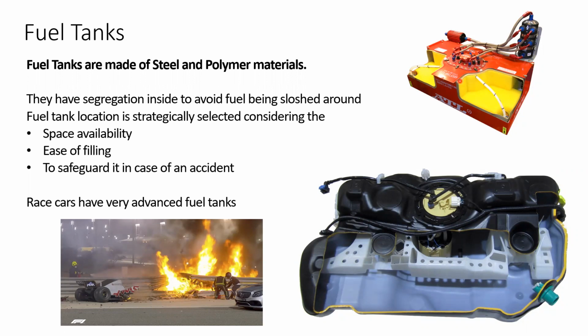Even if the vehicle turned upside down, the fuel will not actually come out. Even if there's a rupture or something, the fuel does not start to leak because it's actually absorbed by these foams. That's how fuel is actually stored in some racing. It depends on the racing class and what the regulations state there.